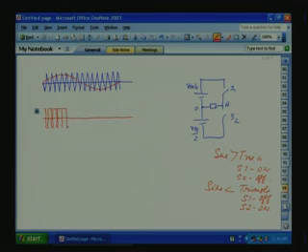We have also analyzed in the context of front end AC to DC converter that the output fundamental will be proportional to the sine wave. And using the odd symmetry here and with the large carrier frequency, this is not only proportional in amplitude, the phase also. In all respect, it will be exactly proportional to the sine wave fundamental.